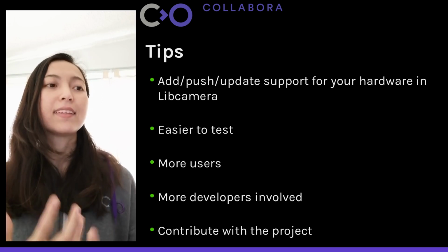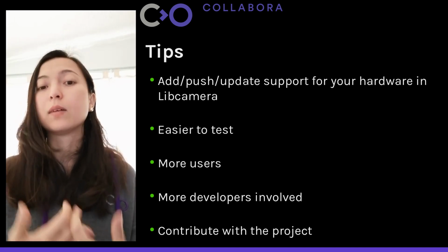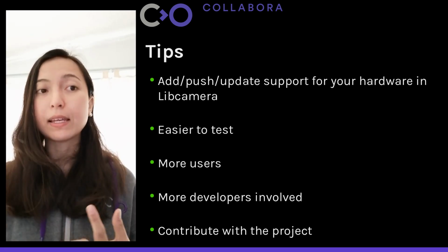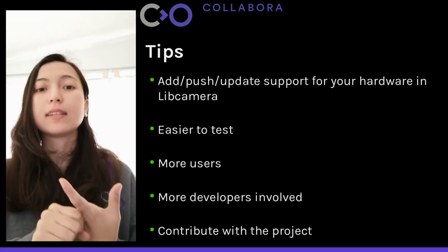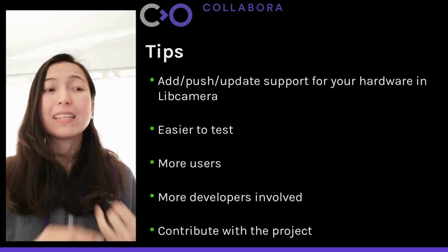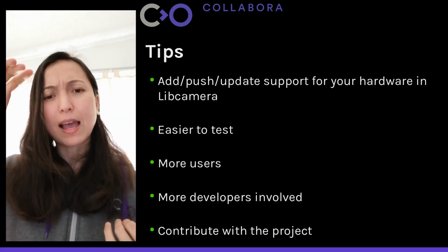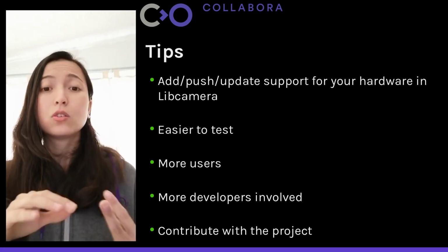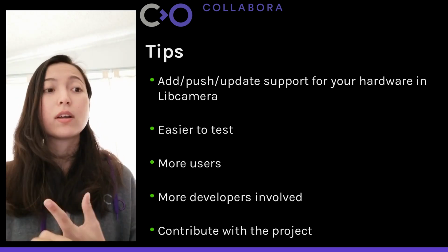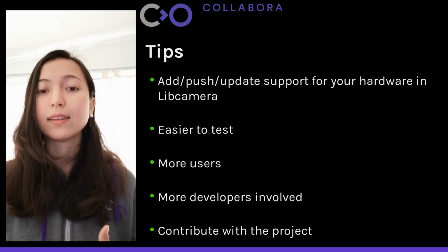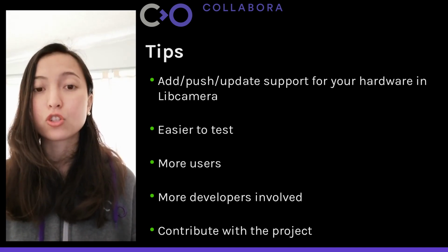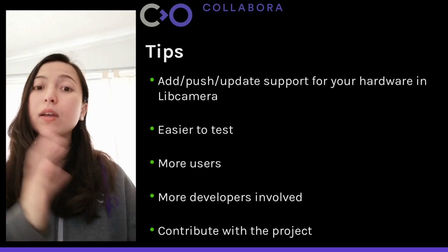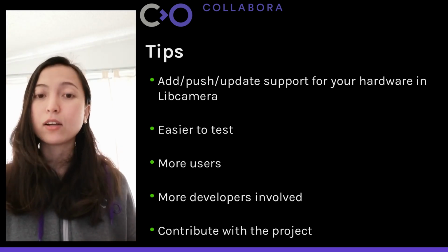A tip that I can give you is, if you are working on upstreaming an ISP, I recommend you add, push, or update support for your hardware in the libcamera project. It makes testing easier, because sometimes configuring the whole topology is very painful. You get more users and more developers involved, since libcamera is a very recent and very active project. People are involved on both sides, in libcamera and also in the kernel community.